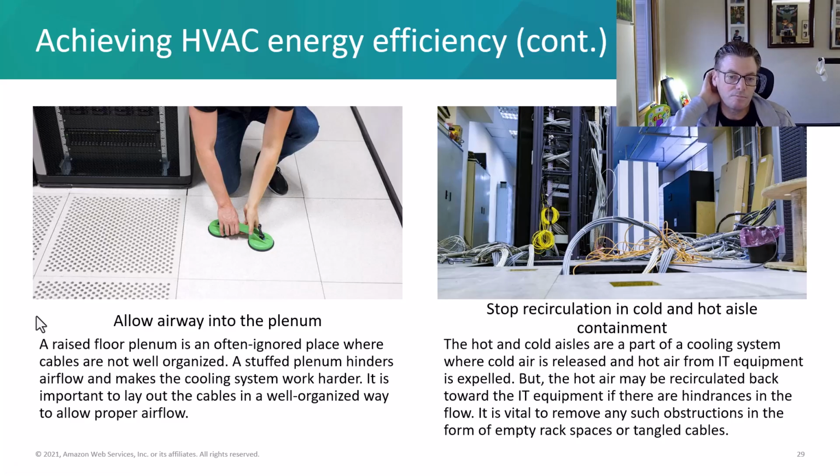All right, raised floor plenums. We've talked about this before. This is a place where we can have airflow go through. So it tells us that if it's overly full, it can restrict airflow, making it more difficult to cool. So we want to make sure that we lay out our cables and everything that's under there properly.